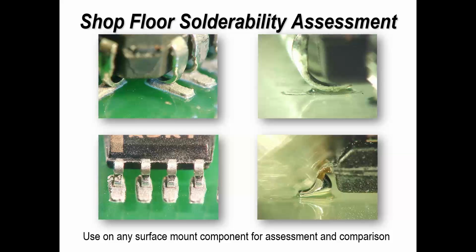So I use a really cheap test which works. This is a solderability test I've used for many, many years because it can do everything. It can do area array, it can do all types of components. Basically, you take a glass slide, you print paste onto the glass slide, you place the component onto the solder paste, and you reflow it through your reflow oven. Same stencil thickness, same paste, same part, same profile you normally use for these types of parts, and that will give you an indication of how well it's soldered.